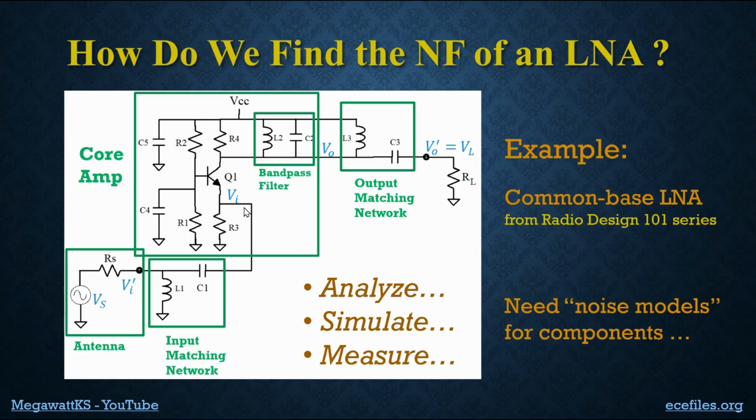And as you look into this amplifier, it has perhaps a different impedance than 50 ohms, and so we know that impedance matching might be helpful to get as much of the signal power as possible into the thing. That'll probably help our noise figure. And so we have a matching network. And likewise at the output, depending on what you're driving into, let's just assume we got 50 ohms here, we can match down from whatever the impedance level is at the collector down to 50 ohms. So we got two matching networks. And the question is, how much noise is introduced by all these circuit components?